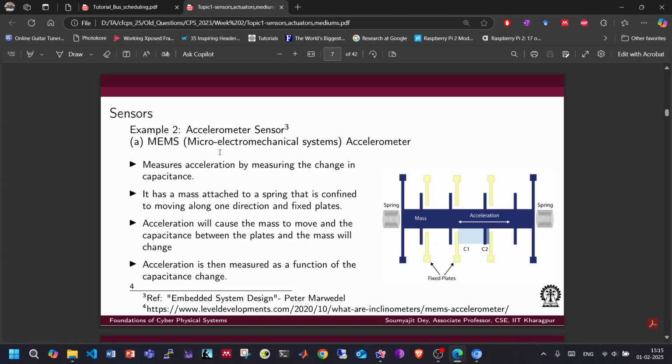It is called proof mass or seismic mass. This is a tiny suspended mass that moves in response to the acceleration. When you are moving towards a certain direction, it is also moving, and when you stop, it understands that you are stopping. Based on certain phenomena we measure how much speed we were moving with, and with how much force we are braking and stopping.